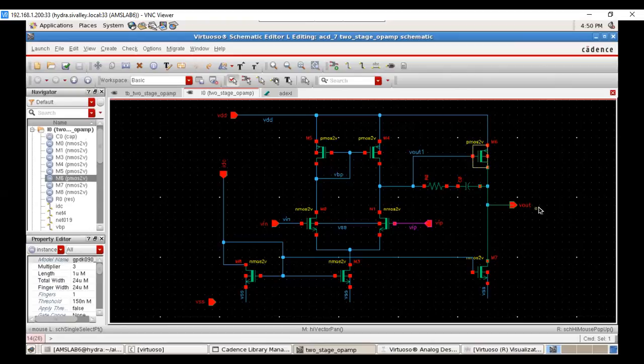Okay, this also has the load effect, that's CL. So the formula we just saw: the resistance that we have to keep here is equal to 1 by gm6 of this, that is the common source amplifier input MOSFET, times the total load capacitor plus CC, divided by CC. Since it's a capacitor, it will be a reciprocal of your normal resistance equations.